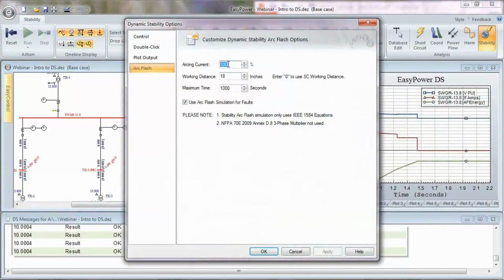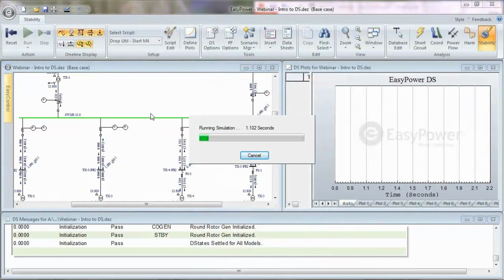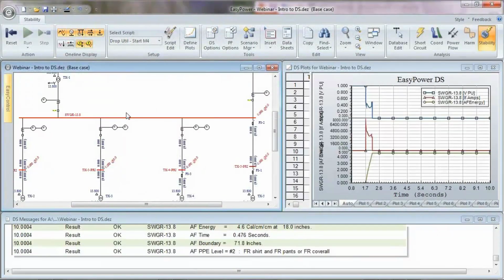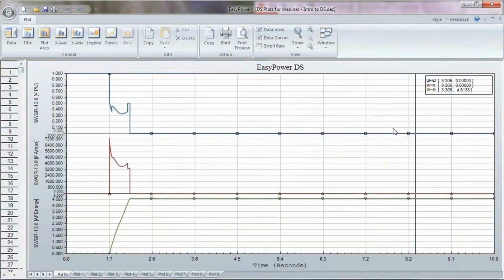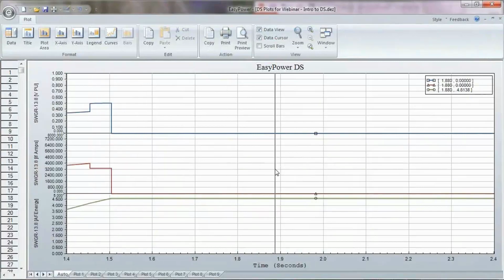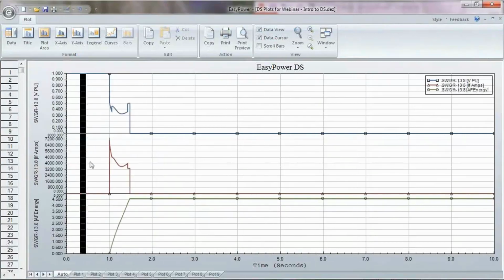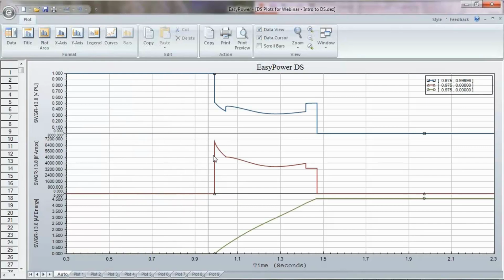What would happen if we were to change this to 85%? Wow, significantly different result. Different tripping time. Completely different behavior. Much different due to, you can actually see the AVR response in here. Look at that. You can see the AVR affecting fault current. And then it trips only briefly and then goes off.